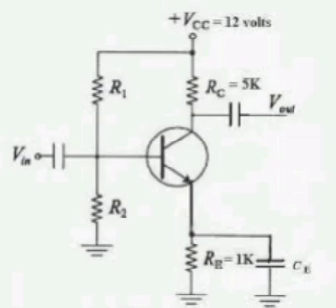When the unknown resistor Rx equals 0 ohms, A and B are shorted, and the meter current is zero. If the unknown resistance Rx equals infinite and A and B are open, the current finds a path only through the meter, and by selecting a proper value of resistance R1, the pointer may be made to read full scale. This ohmmeter therefore has the 0 mark on the left hand side of the scale, no current, and the infinite mark on the right hand side of the scale, full scale deflection current.